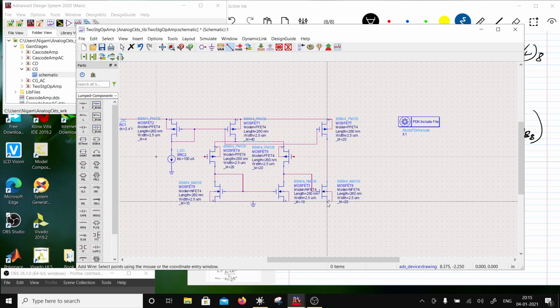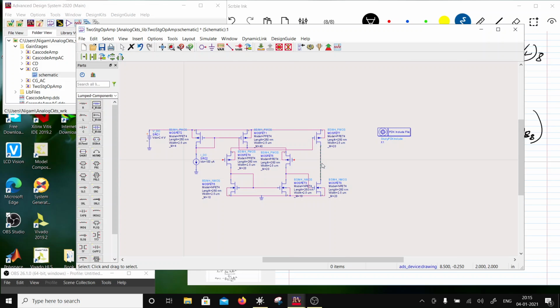So the output voltage range is going to be okay here. Now this is done, this is my output voltage, and I can drive capacitive loads with this. I cannot drive resistive loads because I cannot draw a lot of current out of this. So for now let us test this. To test this, this is my non-inverting amplifier side and this is my inverting side.